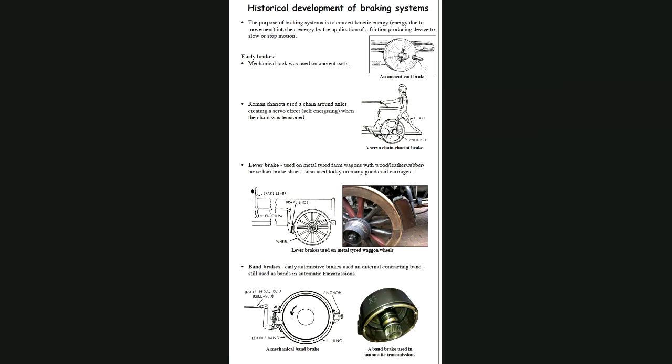It's worked by the ECU of the car, the electronic control unit. And then when it gets up to a certain speed, the ECU releases this solenoid and immediately connects the solenoid to the second gear band. And that's how the band brakes work. And this is a band brake from an automatic transmission.